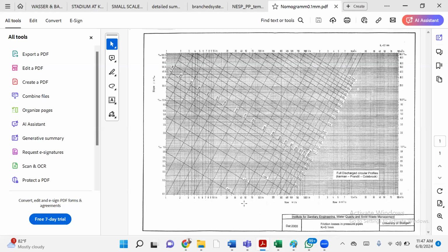Let's get me the one for the 10 hectares. Everybody, in 1 minute, what is the value for the 10 hectares? 18.5 liters per second. Yeah, the same. It's flat land. We calculated it to be 18.5 liters per second. What's the pipe size? The same slope, 5% slope.